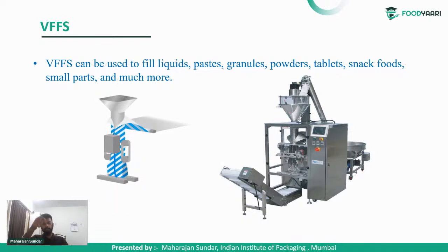Fin sealing will be provided first. Fin sealing in the sense, for example, if we take a milk packet, there will be a seal in between the package. That is known as the fin seal. Okay. After the fin is sealed, then what will happen? End seal will be there. End seal is the bottom package seal.